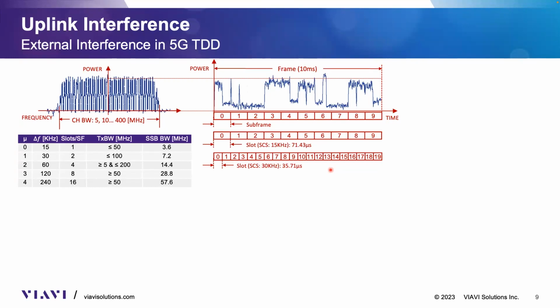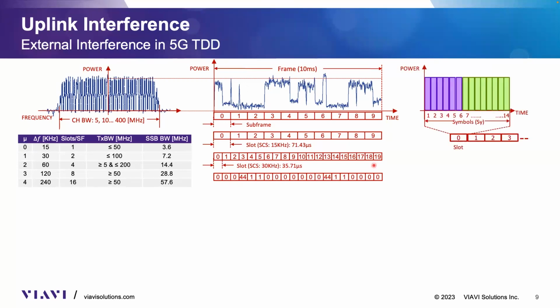And I'm pointing this out because doing the analysis of 5G interference uplink, it's a bit more precise due to this reason in mid-band. So, for example, here we have the assignment of different frame types that can be done by each of these slots, which, by the way, each slot contains 14 symbols, okay?